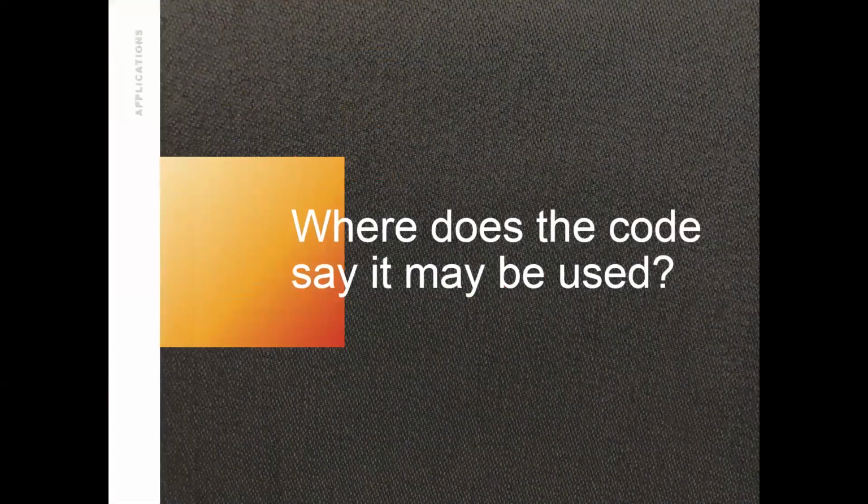We're very upfront about this. Fabric product is exclusively used in 20-minute rated UL 10B assemblies based off of that hose stream test, because it's all about the life safety of occupants. That's what we're discussing, that's what we're concerned about. Fabric product is never to be placed in applications greater than 20 minutes under UL 10B because of what you just saw. So where does the code say it may be used?